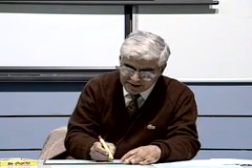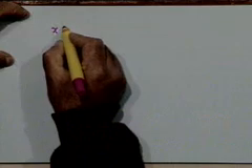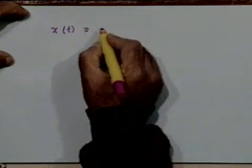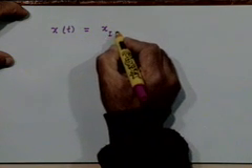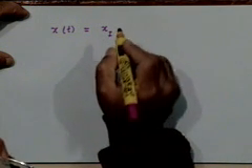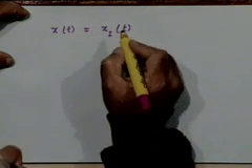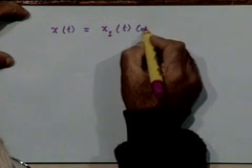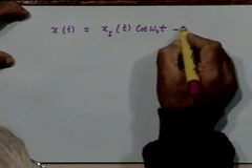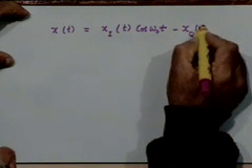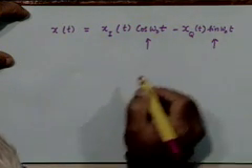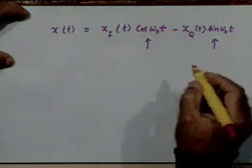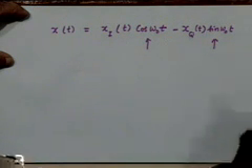Any questions? Okay, let me explain again. I am saying that for any band pass signal x of t, we have found a representation. Let me slightly modify the notation here. Let me call the real part x_I(t), although it is a little confusing, but if I want to talk about in phase and quadrature phase, this is more appropriate, into cosine omega naught t minus x_Q(t) sine omega naught t. These two carriers are quadrature components of the carrier e to the power j 2 pi f naught t. They are the real and imaginary parts.